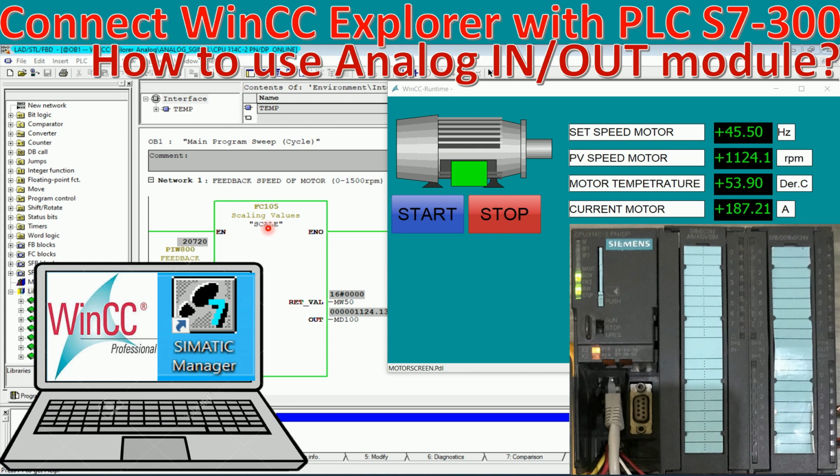It means that we can use FC105 to show the speed of the motor and the current of the motor, and we need to use FC106 to send the set point frequency of the motor to the VFD. And we can learn how to calculate the actual temperature from the AI of this module.